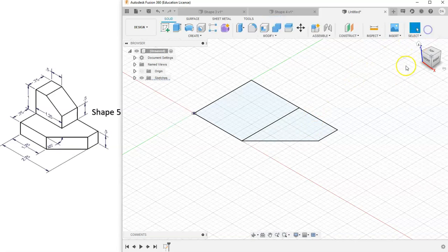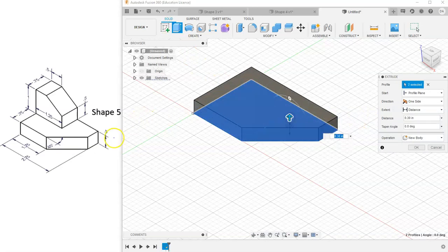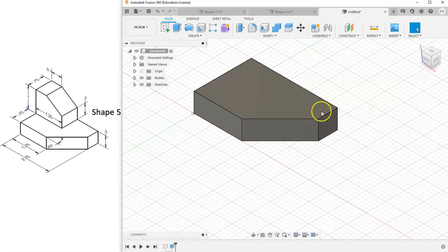Let's go to Finish Sketch and hit Extrude. And what I can do is I can just select both of these shapes together in one and drag it up. And now it just extrudes as one body. And so how high does it extrude up? Well, it goes up 0.5, and so I'll type in 0.5. And we built this bottom platform here through purely additive means. We didn't cut away anything. We just added to our extrusion.